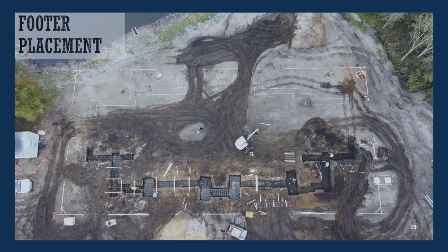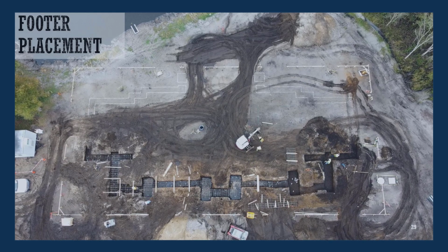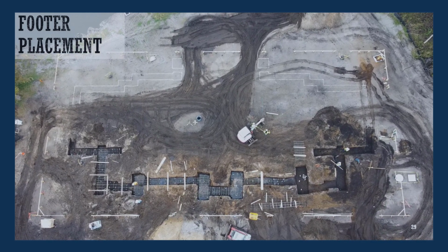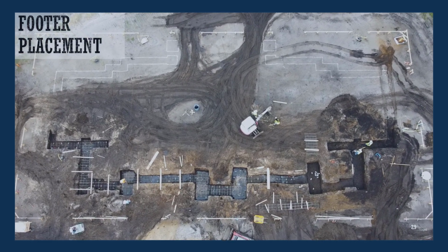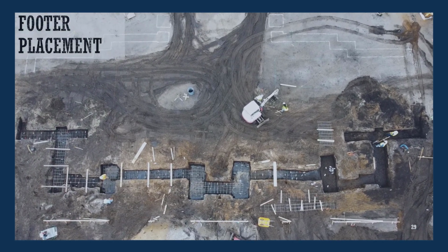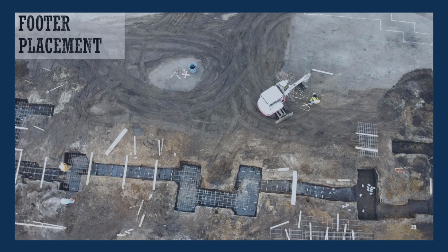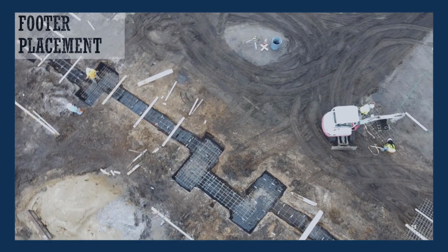Okay, now we have our excavation crew finishing up the trenches for the footings and another crew tying rebar and dropping the mats and cages in the hole. Two carpenters are placing dowel supports and the rod busters are carefully placing dowels so that they end up in the specified cell of the concrete masonry unit. Masons are chomping at the bit to get started and we need to place the concrete ASAP. We are not in the business of wasting money, so we need to accurately calculate the concrete and double check our concrete submittal with what is specified on our plans and specifications.